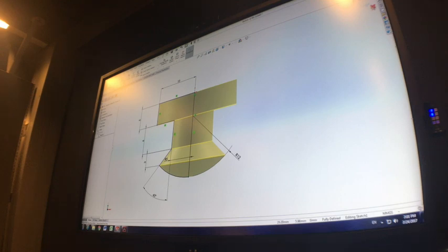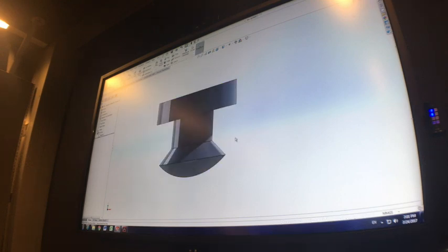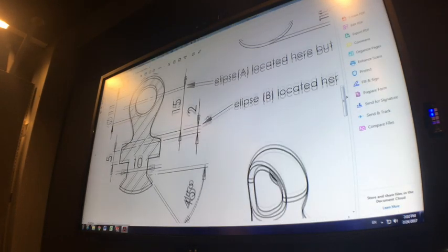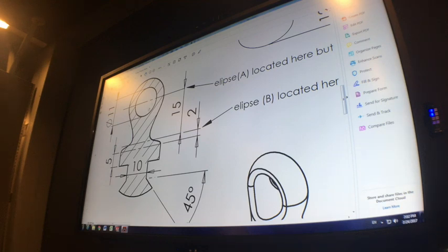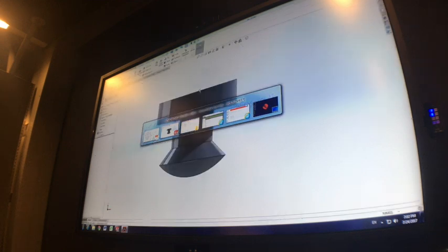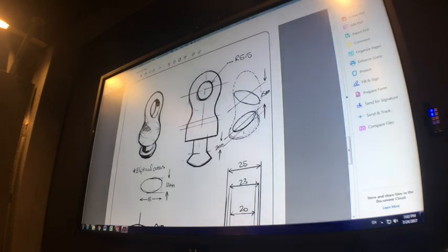All right, so next steps after that, we now need to create this mill section, which is the loft. Lofts always require more setup before you can do them. It's not like a revolve or an extrude where you create one sketch and then just do it.